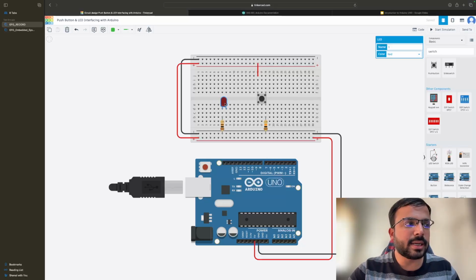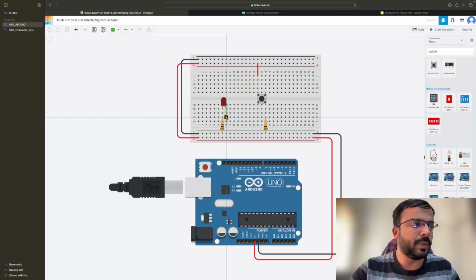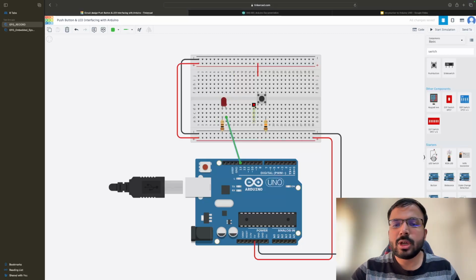But now let's connect this LED first. We have taken a resistor, and we connect this to the negative port, 0 volts here. We said we'll take pin 13 and configure it as an output to drive the LED. So let's connect this. Now this is connected, but this circuit will always be connected to the LED from the Arduino. It is not interfacing through a switch yet.